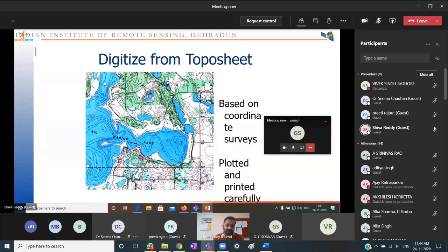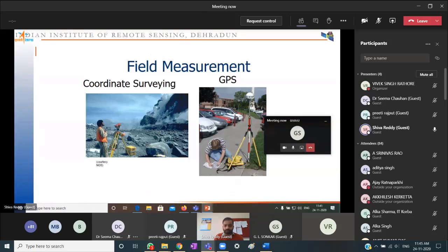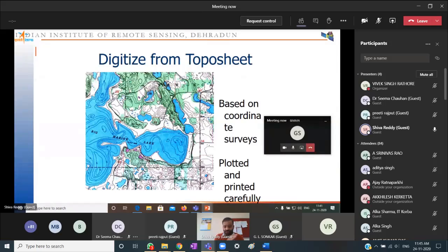Each contour tells you about the height, and based on the measurement you can understand the height of different things. Similarly, based on the legend you can identify different features. The blue areas represent water. Similarly, forest and other areas can also be seen using the legend. So these data are there. Now if I want to bring them to GIS, I have to do a sequence of tasks. First, this needs to be scanned and brought into digital form. Then we will do the digitization, which we'll understand later. So this is one source, topo sheets.